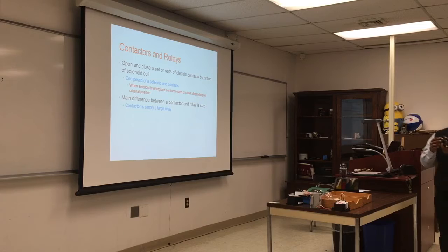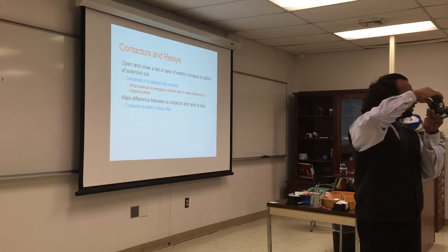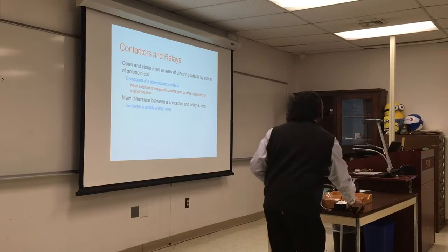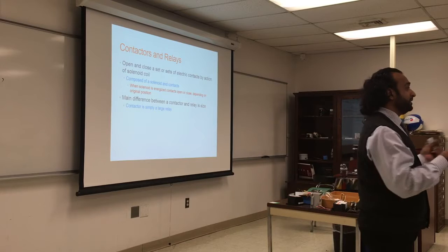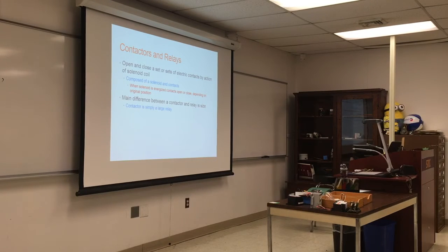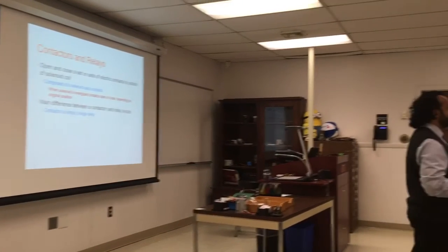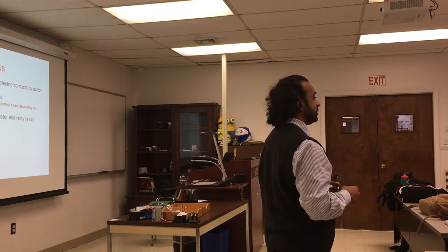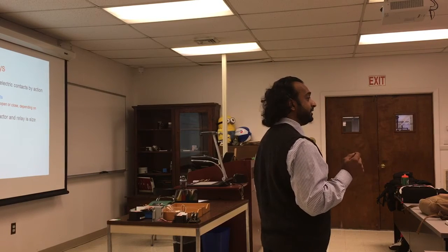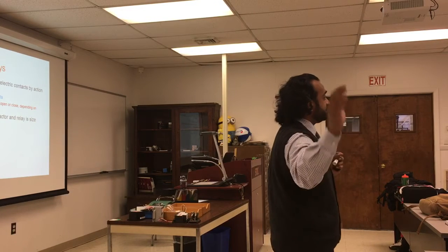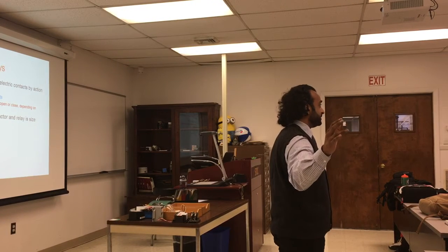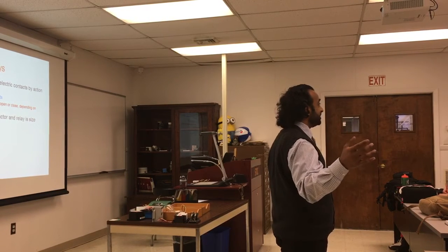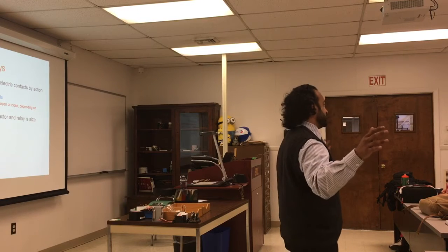So it is a solenoid. That's the coil over here. It goes on and off. So once you energize the circuit, you'll connect all the other circuits. And sometimes you can connect some circuits and disconnect others. For example, in the AC example, or the fridge, we have a lot of frost. I have a sensor that was able to see that there's a lot of frost. What happens? I will activate the relay. The relay, once activated, will disconnect the compressor and engage the heater. Otherwise, you're going to have the heater and the compressor working at the same time, which will cancel each other. So sometimes you want to cancel one circuit and engage the other circuit.